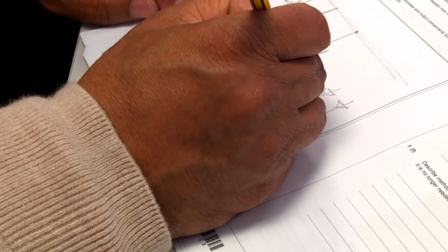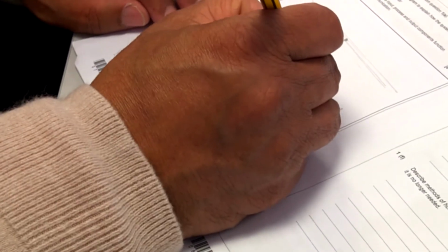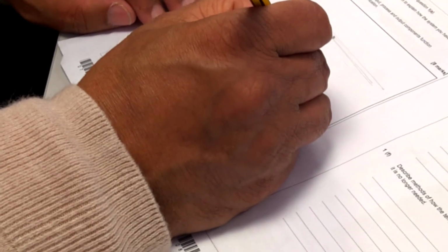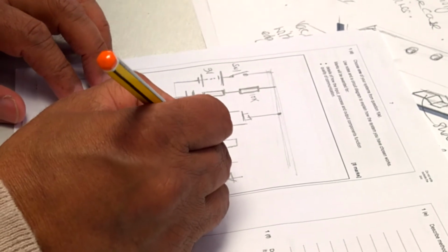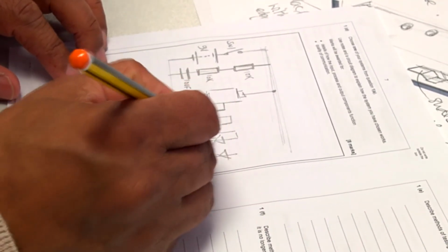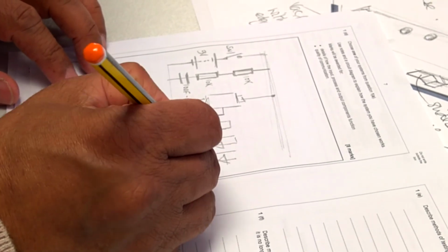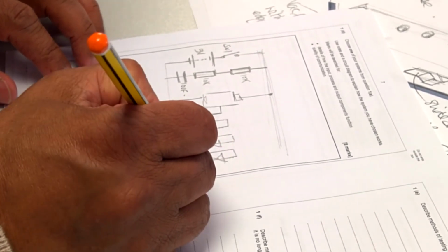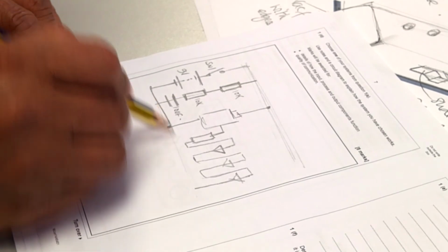Yeah, so from the end of the resistor it goes to the top of that one. So I thought you said use a decade counter for flashing. Well, we went for that, you know, it says choose one. So I've chosen the 555. From the bottom of this one to the top of that one, from the bottom of this one to the top of that one, and the bottom of this one, bring to ground.